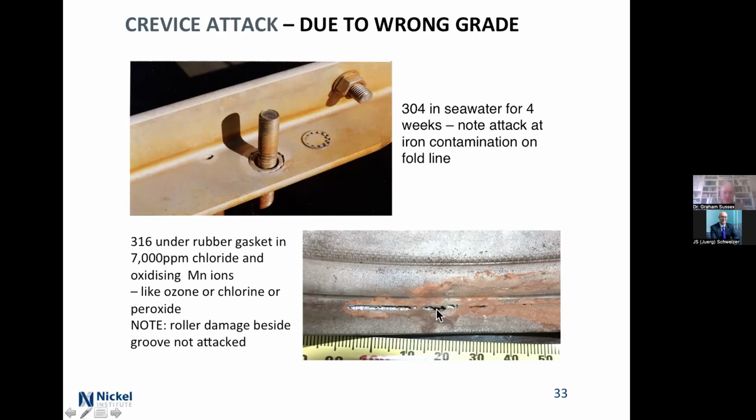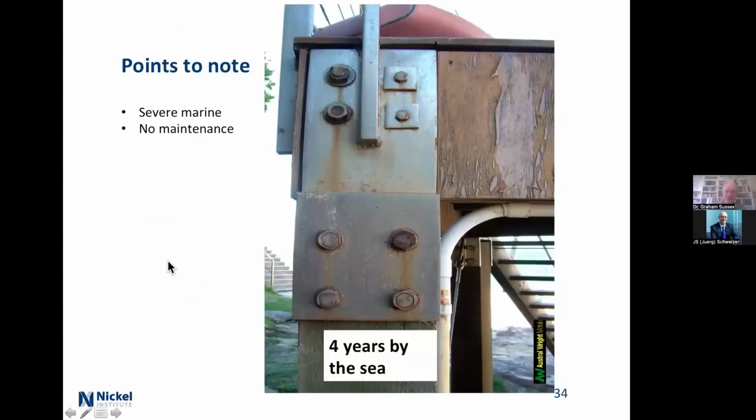Okay. The obvious thing is put in super duplex. I hate to say it, but I think what happened was that they put in heavy galvanized and thin. Said, well, it's going to last for 5 years, so it'll be all right. No comment. This is down by the sea. This is Sydney North Beach, and 4 years. So you've got a 304 bolt there, obviously, but you've got crevices there. No maintenance, fairly severe marine, a week from the crevice, 304 bolt I've talked about.